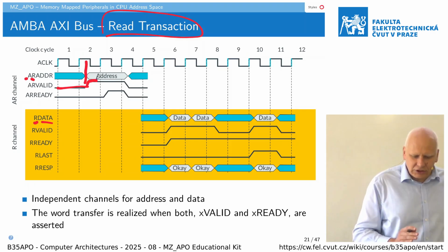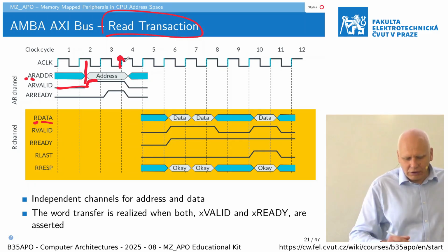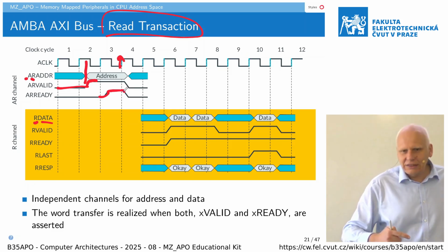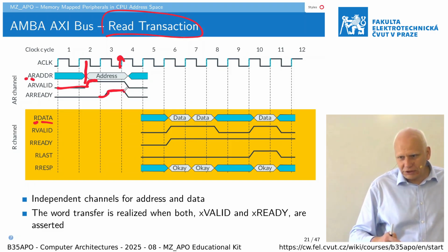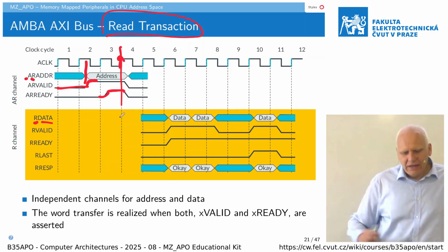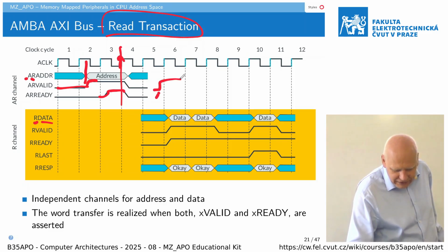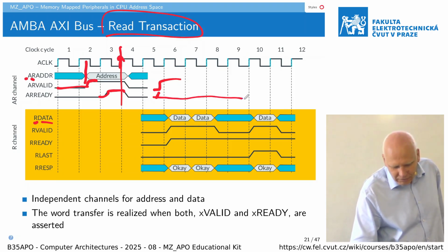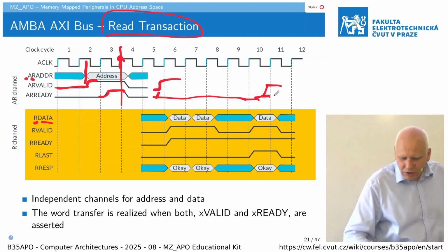But the transaction is considered complete only if at the given rising clock edge the ready signal is asserted by the target of the operation. At that moment we consider the address accepted. In fact, we can try to assert a new address even before the data are returned, but usually it will result in not-ready from the target, which informs that it will be ready only somewhat later.